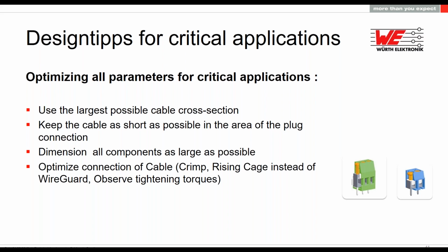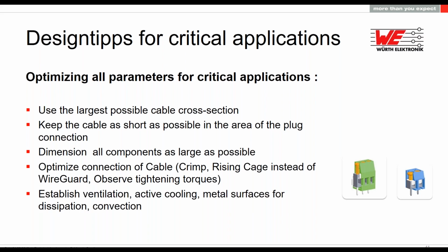And also rethink probably your ventilation system. How closed and how small is your housing? Do you need active cooling? Is it okay if you can build some metal surfaces in the housing that can bring heat to the outside, like aluminum cooling bodies, things like that, to get a stable heat environment.